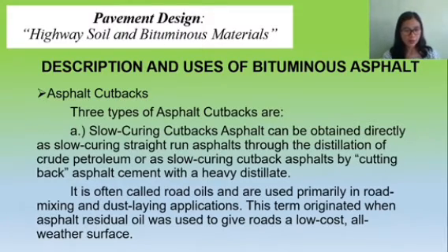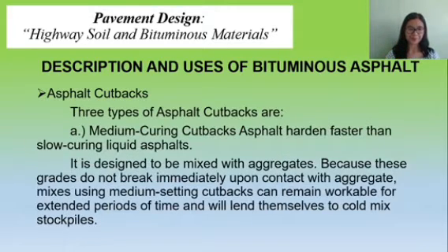It is called road oil and is used primarily in road mixing and dust laying applications. This term originated when asphalt residual oil was used to give roads a low-cost, all-weather surface. Slow curing cutback asphalts are also used for stockpile patching mixes, plant mix with graded aggregates, and occasionally for priming.